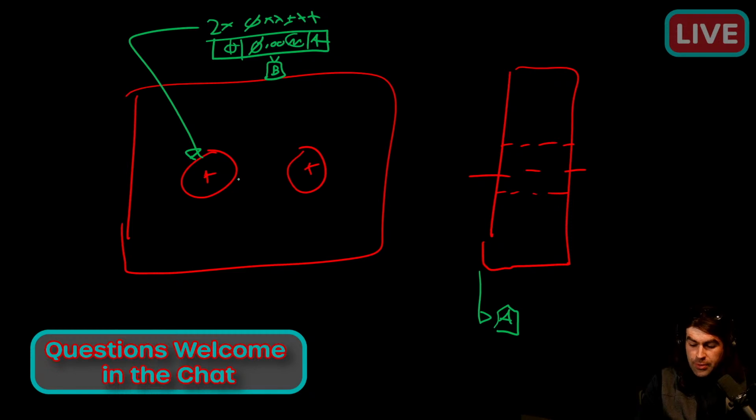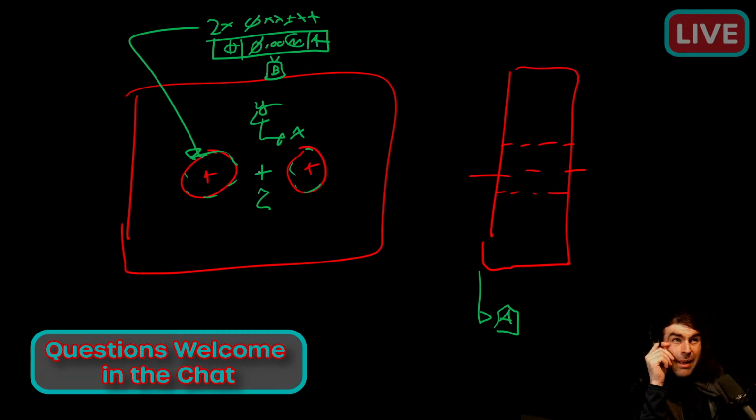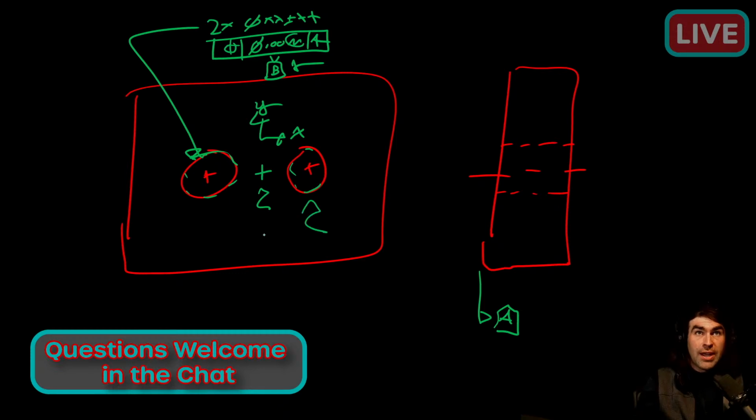Well, with Calypso, you could do it a couple different ways, really. You could capture each of these features. So you could do 2 circles and do a symmetry point and treat this as the, say we're going to do it like this, say X and Y. You could treat this as your 0 for X and Y. And that's probably what you want in this situation, because it's going to give you reasonable results for how far this hole is away from the center of the part.